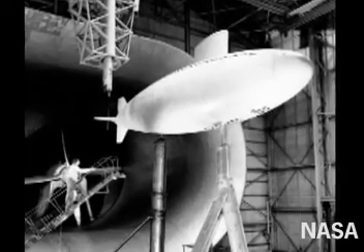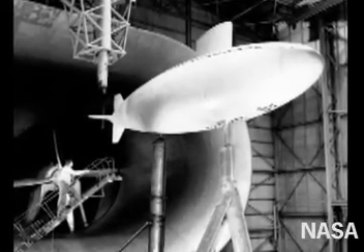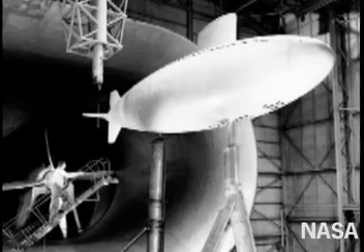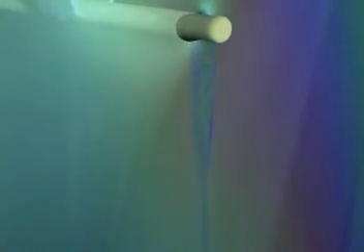Depending on the Reynolds number, some flows have different regimes with different flow patterns. The classic example is the flow over a circular cylinder, illustrated here using a soap film tunnel. At low Reynolds numbers, between about 4 and 40, attached vortices form behind the cylinder. Above about 40, we see the famous Kármán vortex street, the alternate shedding of vortices from one side of the